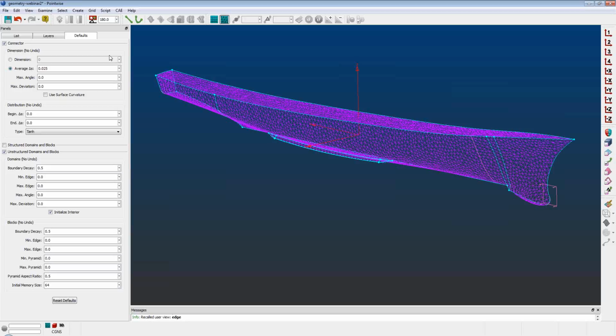I was just wondering how big the gaps could be to use the two methods to fix them? That's probably up to you, but a rule of thumb is you definitely don't want to heal gaps larger than your mesh level. So, definitely just a fraction of your overall model size. In this case, the model length is about 2, and our gaps were four orders of magnitude smaller.